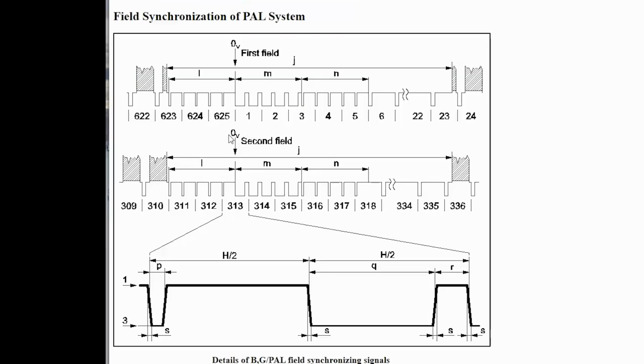Okay, I found this image on martin.hinner.info/VGA/PAL. So after we've drawn all of our active pixels vertically, we need to basically tell the screen to start drawing over again. So that's what the vertical blank is for. Now we don't have a separate signal for that like you would on VGA. So we do it by having, I think it's either 3 or 9 lines, I'll have to check, of just black. Then you invert it. See this? Where you're going from 0 to 0.3. So basically you invert the H-sync pulse, and that's interpreted as the vertical sync. Then you have 3 more lines of black, and then you start all over again.